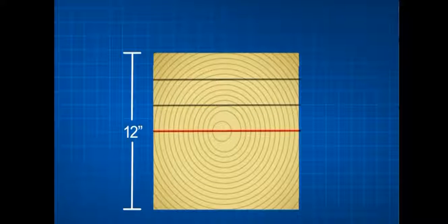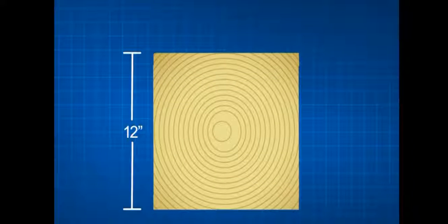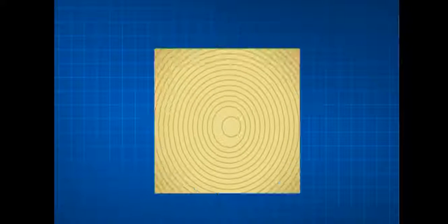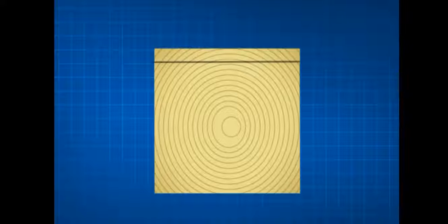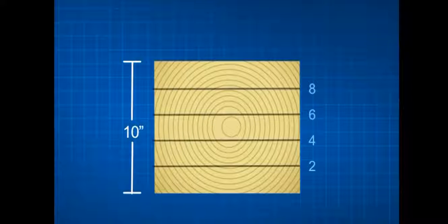That's the middle, that's the halfway point on 12. You can't make that cut at 6. I contend you're better off taking that 12-inch cant, drop to 11, make an inch board, roll 180, drop to 10, make another inch board, and now you've got an odd number of pieces and you can keep the heart in the center, and you won't be splitting the heart.